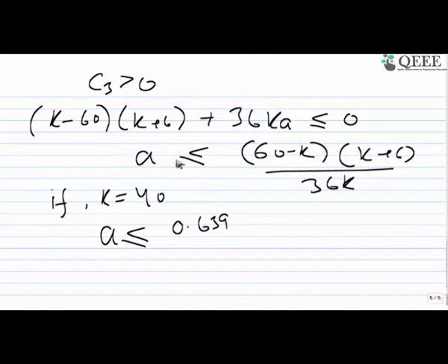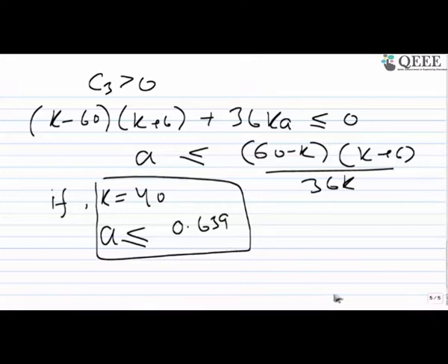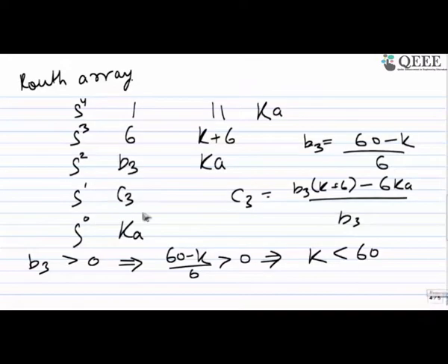So once you start increasing the value, what would happen? You will soon realize that there are some limiting factors implied by the third condition, that this element Ka should be greater than or equal to 0.